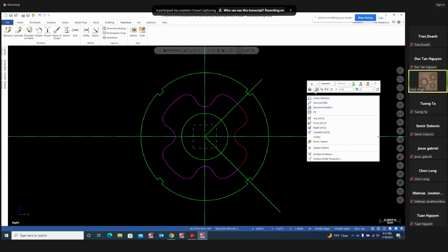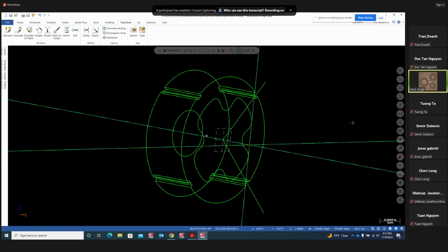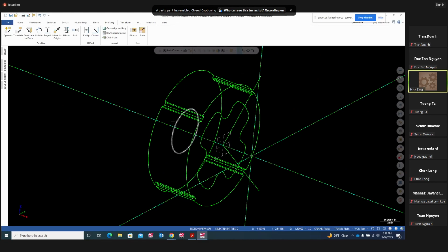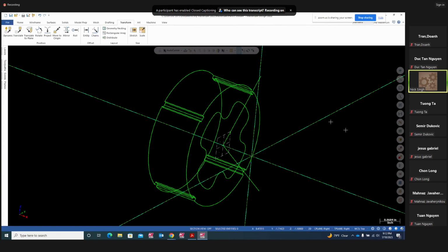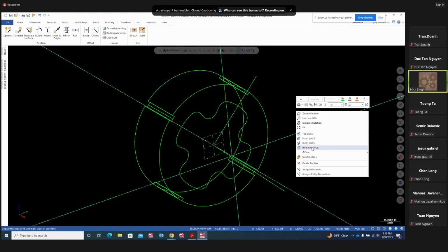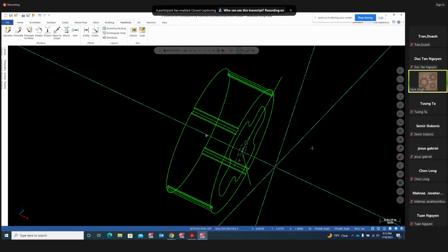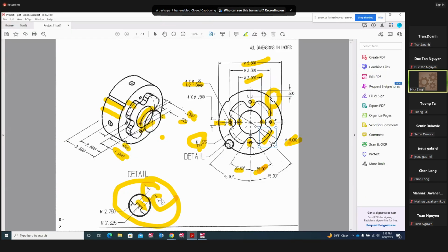Right click, clear colors. So if you look at that drawing, I created that drawing. This Z has to be, this is not good, guys. That was done in 3D, that was the problem. So anyway, if I'm going to look at isometric, I have drawn that flower at Z minus 1.5. So when we're going to create a toolpath for that, now if you look at blueprint, the thickness of this flower thing is 1/2 inch. So I can translate that 1/2 inch.